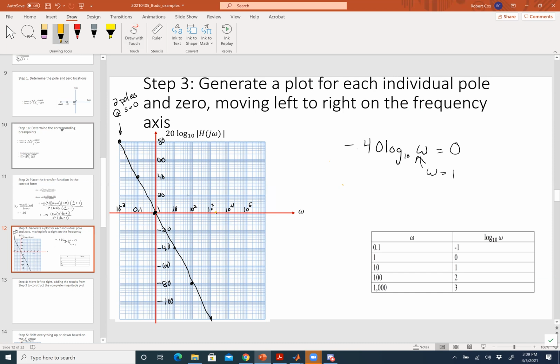At what point is it going to reach negative 20 dB? At what frequency will it reach negative 20 dB? 20,000, right? One decade. At 200,000, it'll be at negative 40 dB. All right, so I'm going to draw this in here like this.